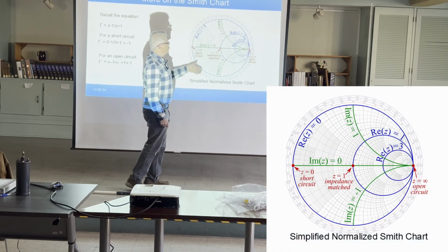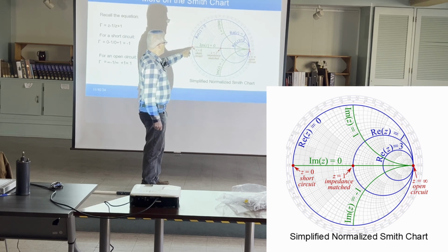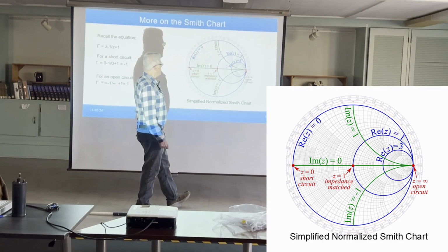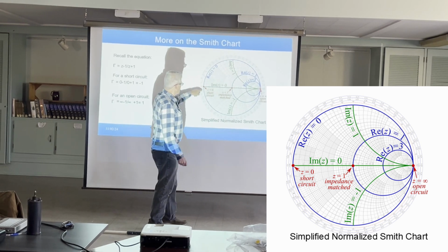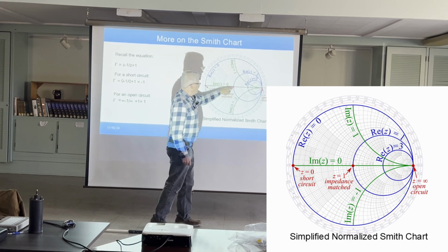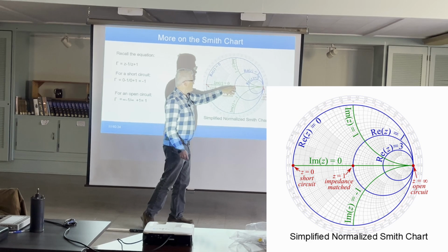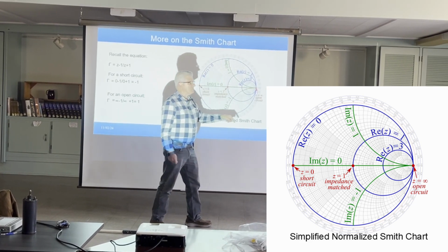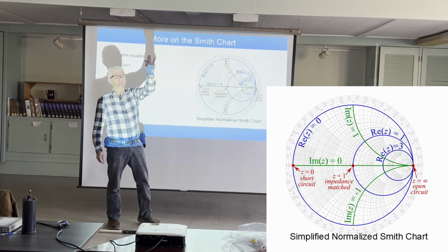So there are three basic components to all Smith charts. Well, this type of Smith chart. There are different types of Smith charts. This line across the center here, which would normally be the x-axis on a Cartesian plane, is the impedance line. And it goes from the left to the right. It starts at a short circuit. Okay, this is zero impedance. Here in the middle is your characteristic impedance, the perfect match. So in the case of 50 ohms, that's represented by 50 ohms. And then over here is an infinite or open circuit. So that's your open.